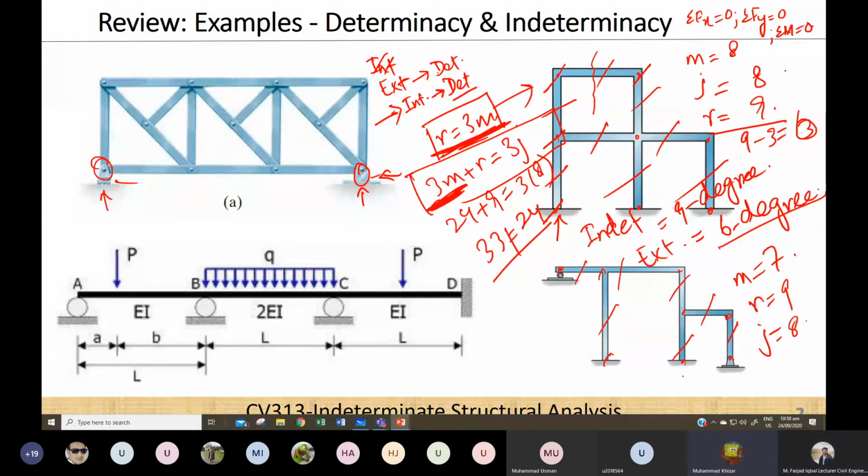सपोर्ट वाली को जॉइंट कंसीडर करते हैं। Joint क्या होता है? Joint जहाँ पे member connect होता है। ठीक है, अब ये member, for example this is member 1, ये कहाँ पे connect हुआ हुआ है? यहाँ पे connect हुआ है, यहाँ पे भी connect हुआ है। तो ये भी एक जॉइंट है, ये भी एक जॉइंट है। इस पॉइंट पे भी फोर्सेस होंगे। सिमिलरली ये अगर मेंबर 2 है तो ये यहाँ पे भी कनेक्ट हुआ है और इधर भी कनेक्ट हुआ है। इधर से भी इसको फोर्सेस ट्रांसफर होंगी। तो जहाँ से भी फोर्सेस ट्रांसफर हो सकती हैं वो एक जॉइंट है।